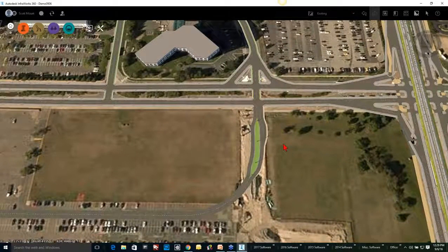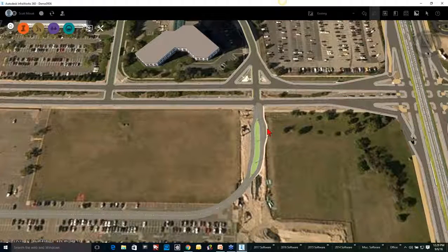The nice thing about this is, again, you can build this from scratch, piece by piece. I could have come in and I could have made this lane right here, instead of 2.5%, I could have made it 4%. I could have put in a bus shoulder. So if you're talking about a highway, you got your 2 drive lanes, and then you got the bus shoulder, minus 2.5% crown, and then the bus shoulder is minus 3%, minus 4%, and then you have edge of drive lane, so you got that extra shoulder, maybe you have curb, something in there. I have the ability to make those adjustments.